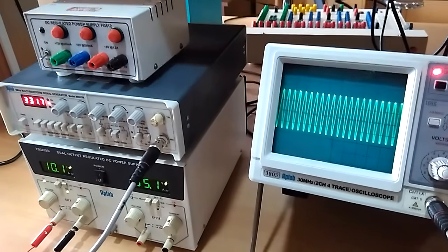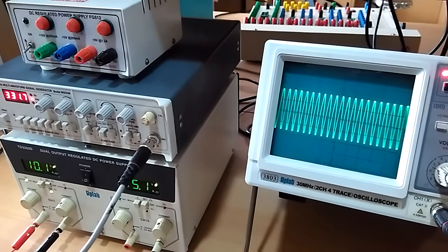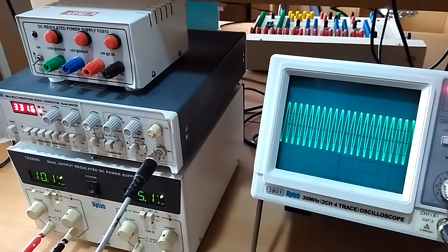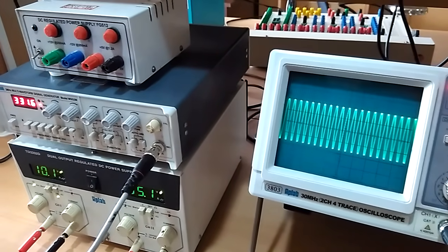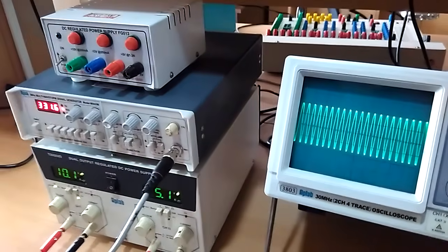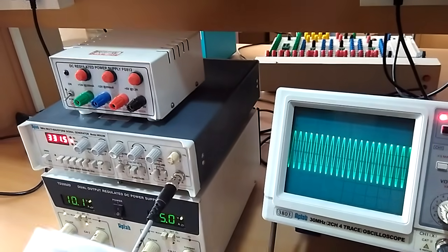Till 4 kilohertz, the amplitude keeps on increasing as the frequency increases. At 4 kilohertz, we will have 4 volts peak to peak amplitude. That 4 volts is maintained constant till 240 kilohertz. Next, from 240 kilohertz, the amplitude goes on decreasing. So the frequency response of the circuit will be like this.